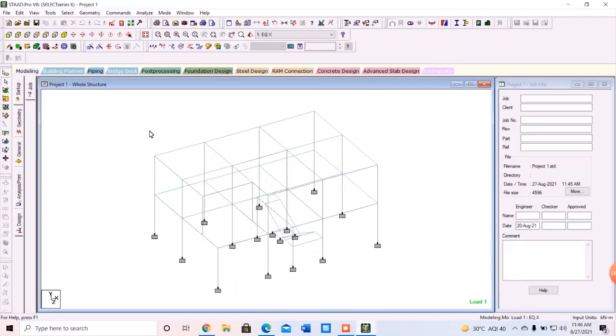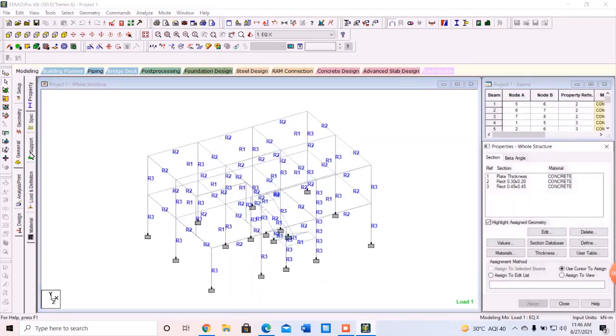While calculating the stiffness matrix, we need member length, member properties, elastic modulus, and support conditions. Using the support, specification, and property subtabs, we have given this data to our structure, and we have already calculated our stiffness matrix.